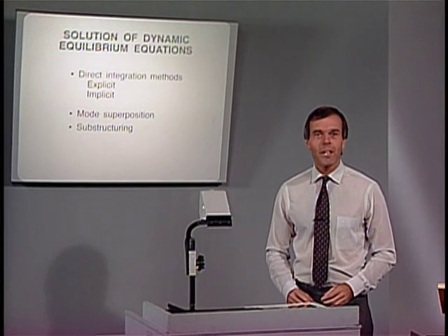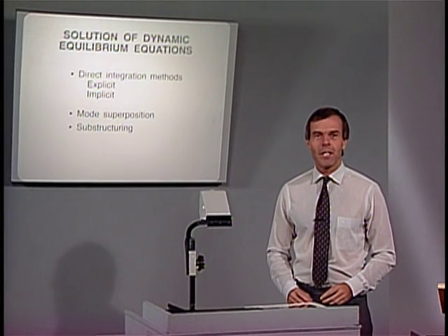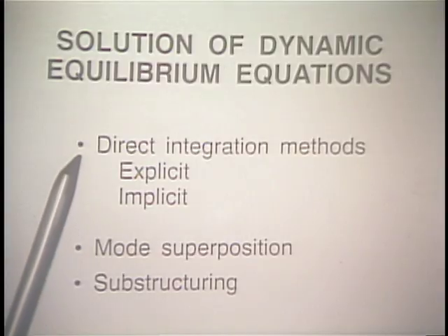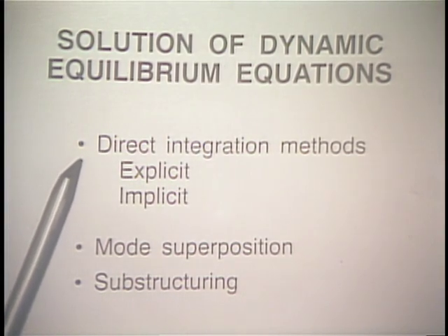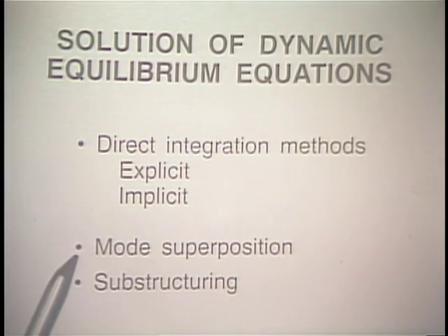Ladies and gentlemen, welcome to this lecture on nonlinear finite element analysis of solids and structures. In this lecture, I'd like to discuss with you some solution methods that we employ to solve the finite element equations that we encounter in nonlinear dynamic analysis. The solution methods that are in general used can be thought of to fall into these three categories: direct integration methods, mode superposition, and substructuring.